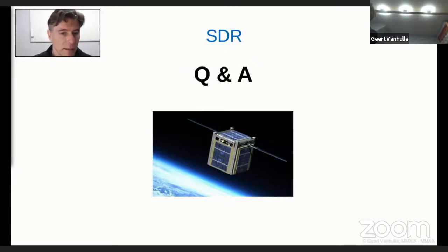One thing to add to that, and it's not really to do with the delays, but one advantage, and these propagation delay problems are an example of it: if you have a software-defined radio and your output stage is producing, for example, a harmonic signal, what you would normally do in an analog circuit is filter it out. You need some kind of filter to get rid of this harmonic signal, because you don't want it to go into your amplifier and your antenna.